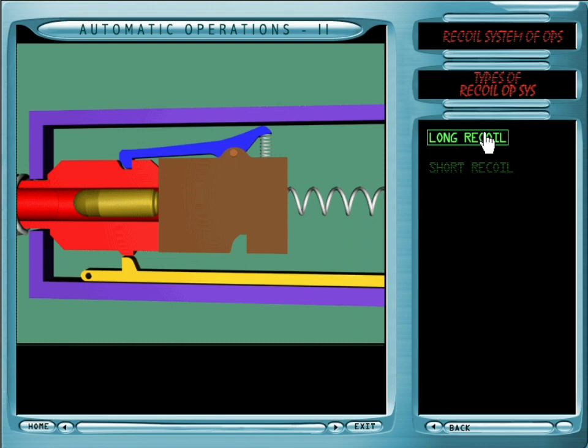Now, extraction takes place. The breech block, on contacting the rear buffer, moves forward and gets locked up with the breech lock. Ejection takes place. The barrel moves forward to its original place and there presses on the breech unlocking device. The breech gets unlocked and starts moving forward. It takes the topmost round of the magazine, feeds it, loads it, and after the toggle joint gets pressed down and the breech block gets locked to the barrel, the weapon is mechanically safe for firing.